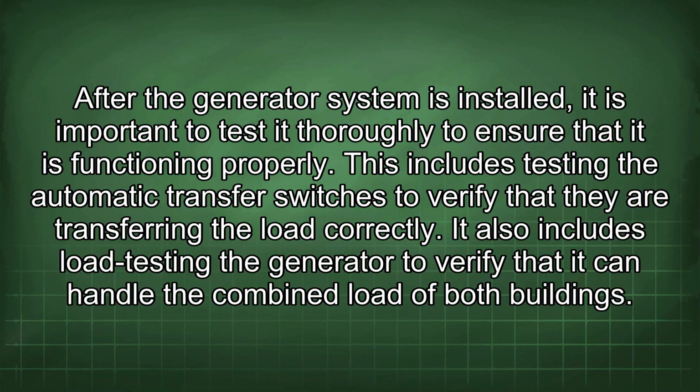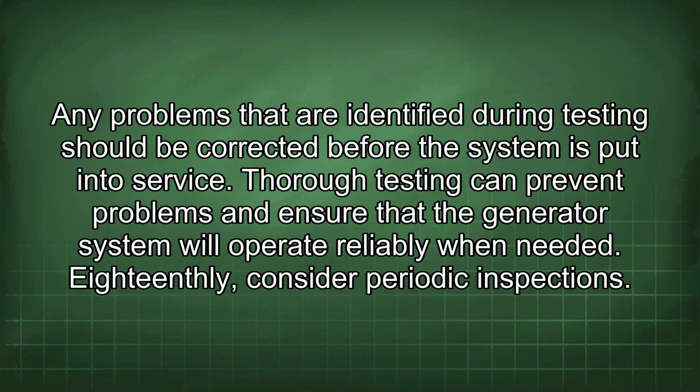It also includes load testing the generator to verify that it can handle the combined load of both buildings. Any problems that are identified during testing should be corrected before the system is put into service. Thorough testing can prevent problems and ensure that the generator system will operate reliably when needed.